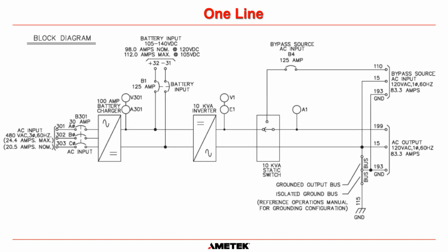So you can see here that the input current is rated right there. Basically, you would have to look at that current and size your cables accordingly, and then size your upstream breaker accordingly. And do remember, for the AC input to any of our industrial systems, you can see here we have A phase, B phase, and C phase. We do not run a neutral.